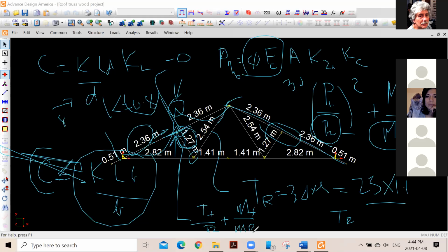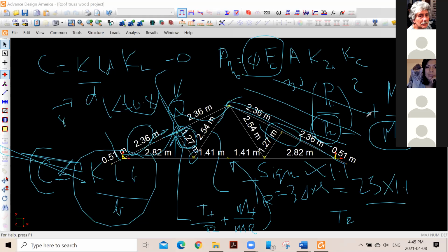But don't forget, now the MR, you go to the joist tables for this one. You take the MR for a single member and you multiply it by 1.1 because you have a case one system, because you're going to have at least 3 trusses, not spaced, you understand. So for the MR for this, you take it from the joist tables, but you use single member and you multiply by 1.1 because you have a case one system. You don't have a case two system because you don't have the sheeting on this one, understand? For the MR value. And that's it.